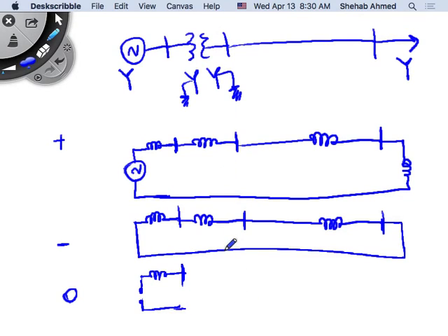What does this transformer look like in zero sequence? It's star with neutrals both grounded with no neutral impedance. So what does it look like, Sarah? Exactly. It's nothing but an impedance. It's a zero sequence impedance of the transformer. There's no open circuit, no tricks at all here. Right? And then the transmission line is also an impedance.